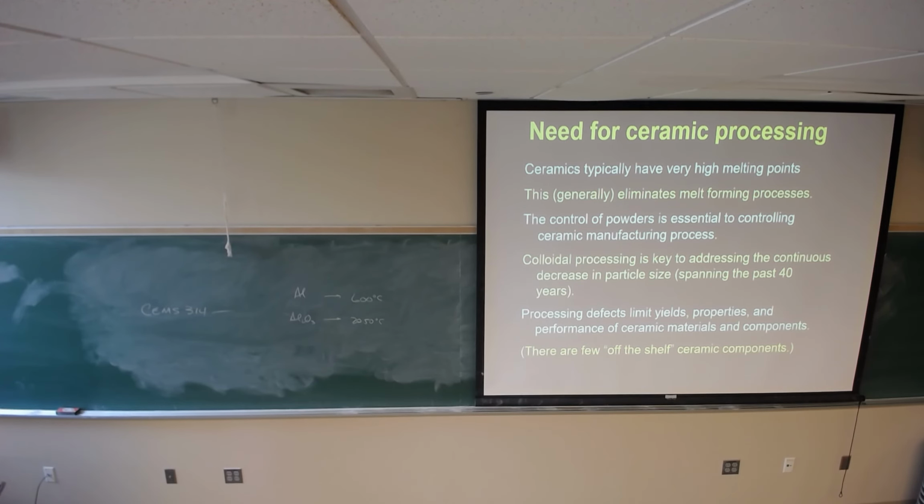If you take my refractories course in the spring, we'll go over to Falconer, New York, to the Monofrax plant, where they arc melt alumina, zirconia, and a bunch of other things. Screaming hot, awesome. They cast these blocks, and then they knock the molds off. They're still glowing red, and they let them anneal for 3 weeks to cool down. How cool is that? Or hot, as the case may be, right? So those are fused cast refractories. Benefit, great for refractory applications. Impractical for everybody else. So we don't do that.